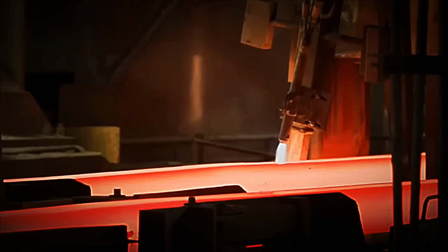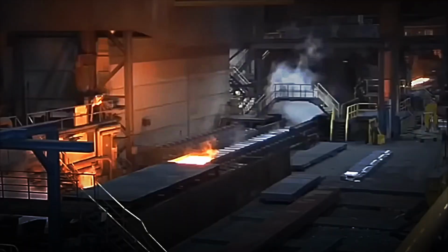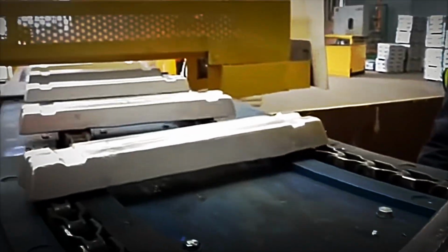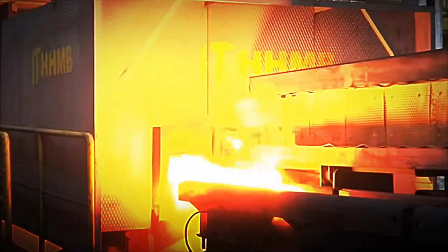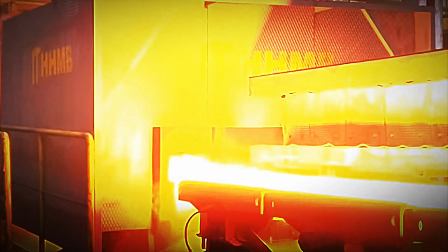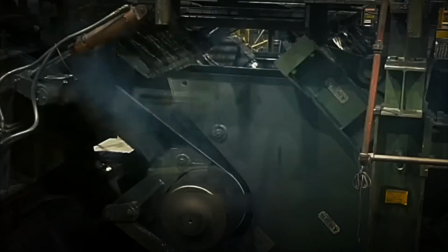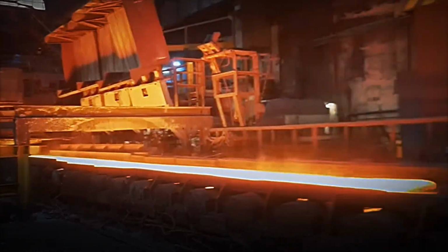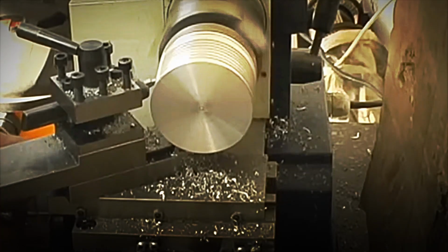When they reach the appropriate temperature, the ingots are transferred to reversible mills equipped with enormous rollers that apply forces equivalent to thousands of tons of pressure. These rollers rotate in opposite directions and progressively compress the aluminum, reducing its thickness with each pass and elongating it into a continuous sheet. The process can be repeated several times until the desired size is achieved. An ingot just a few meters long can be transformed into a sheet that stretches for kilometers while maintaining the strength and uniformity of the material.